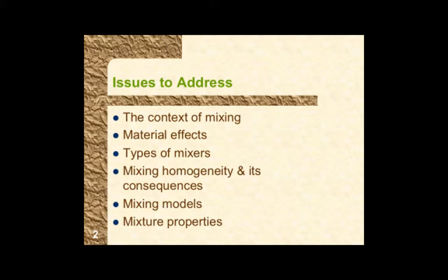homogeneous mixture. But then when you're dealing with melts, you need to heat up the material, and polymers will have a higher viscosity compared to a polymer solution by itself, right? Because the lower molecular weight solvent doesn't exist. So the mixing intensity, the shear force that you have to provide, is going to be higher.